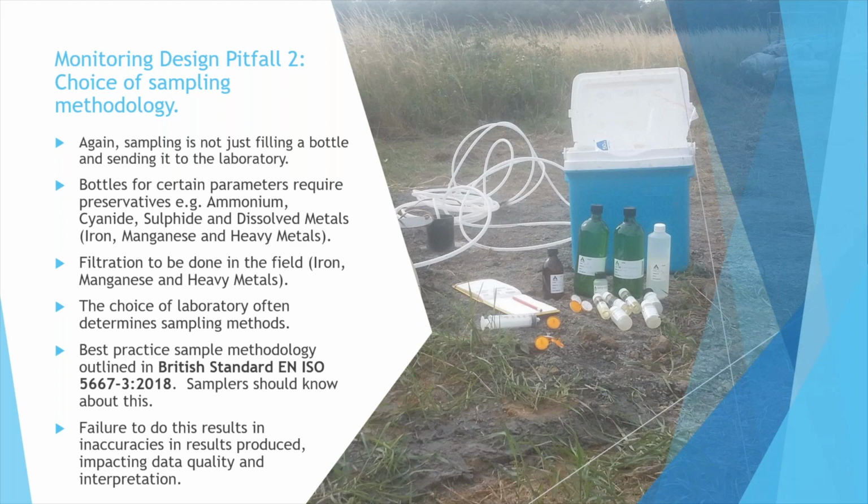Now, the choice of laboratory that you make indirectly determines the methodology that you put in place in the field, because the laboratory will provide you with the sampling equipment, like the filters and the bottles. So in order to avoid this pitfall, you need to choose the right laboratory. At the moment, we're aware of 7 laboratories in the UK, and of the 7, 3 adhere to the British standard, which governs the proper preparation of samples in the field. This is the standard that I've listed here in the slide. The other 4 do not implement this correct methodology.